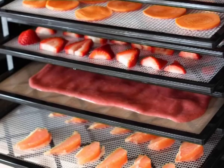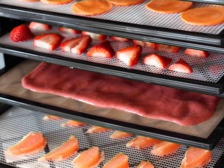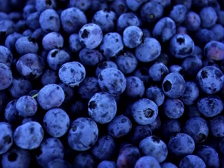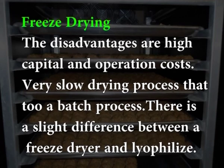In freeze drying, heat transfer occurs by conduction. Most suitable for low volume, high value products, especially those that are meant for export. Typical examples are coffee, strawberry, peach, blueberries, raspberries, caneberries, to mention a few. The major disadvantages are high capital cost and operating cost. Further, freeze drying is a very slow process and often it is a batch process.